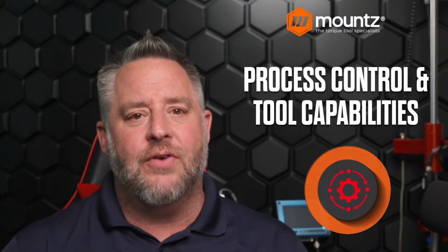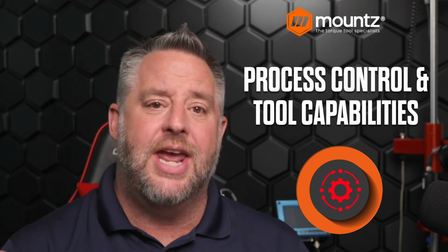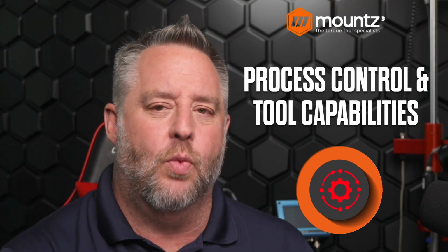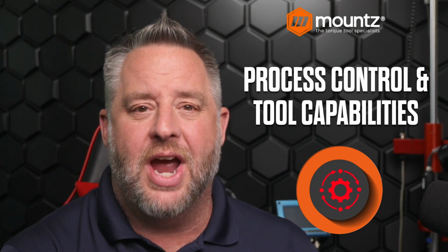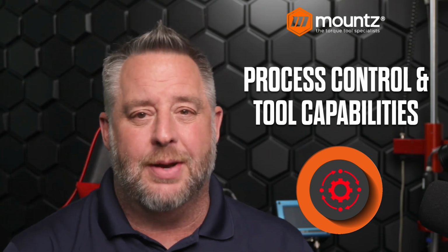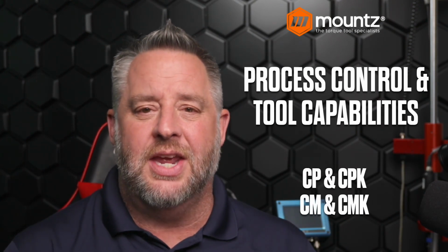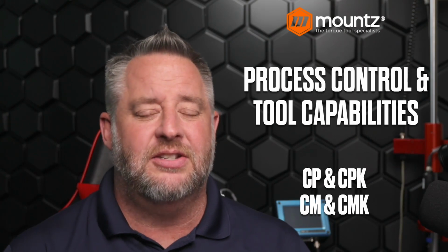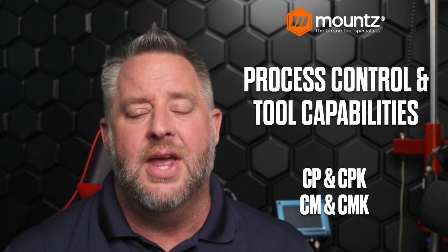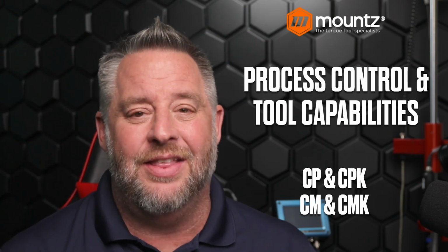And so this all leads us into the ability for process control and tool capabilities. And doing those types of tests can really help if you're having issues with a particular assembly process or the overall assembly of a specific area. What you'll want to do then is your CP and CPK testing. But the first place that you should start is with the CM and CMK testing of the tool that you're using within that particular assembly.